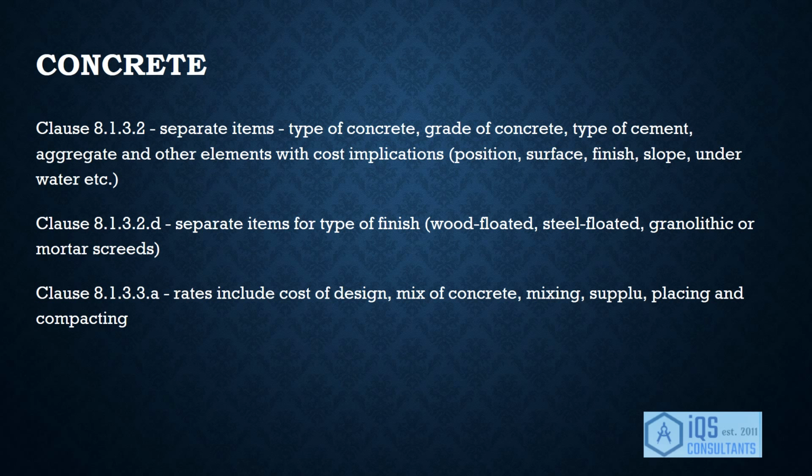Clause 8.1.3.2d furthermore states that separate items should be used according to the type of finish given to the concrete, such as wood floated or steel floated, and granulithic or mortar screeds. Clause 8.1.3.3a describes the measurement of rates used for concrete. It states that the rate shall cover the cost of the design and mix of concrete, the mixing, supplying, placing, and compacting of concrete.